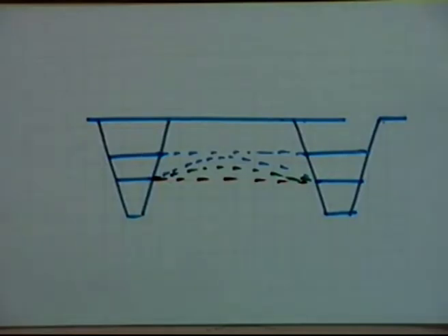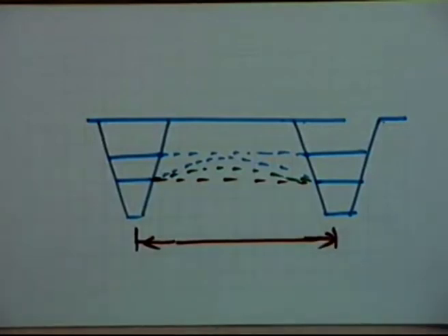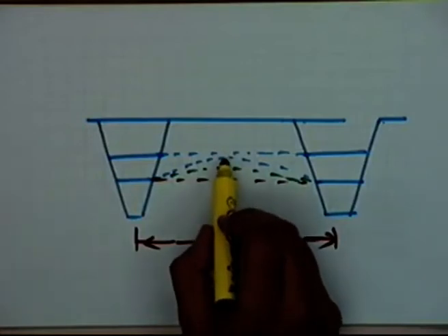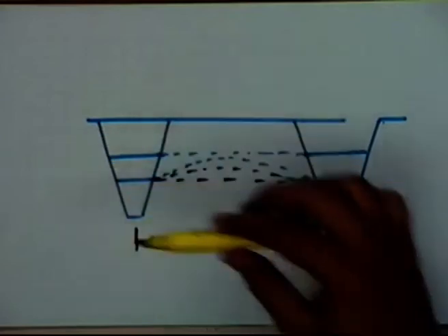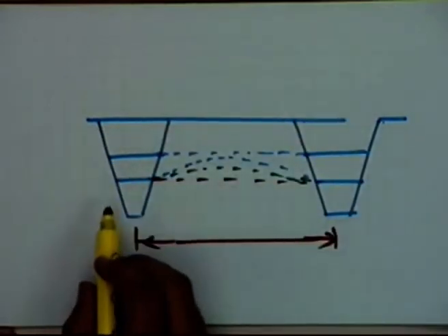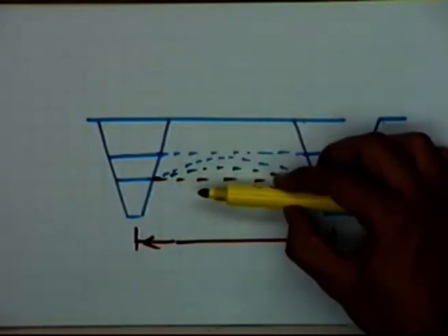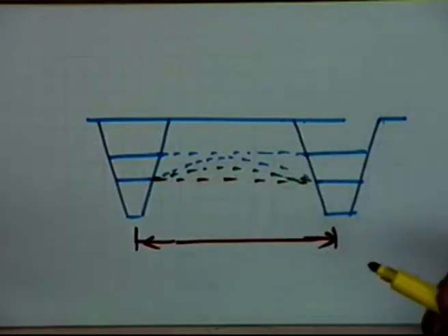The design parameters which you have to look at when you design the subsurface irrigation are: what should be the spacing between the ditches, because that will decide up to what level the water table, when you control these levels of water in the ditches, how much time it will take for the water to drop down to the desired level, how quickly it will do that, because that is a function of the soil type.